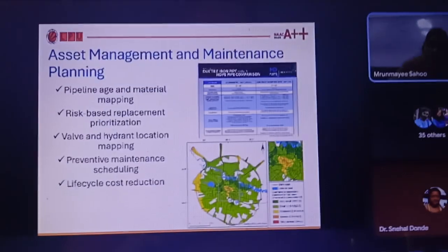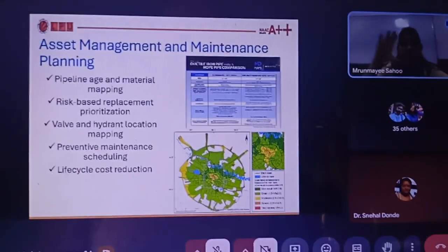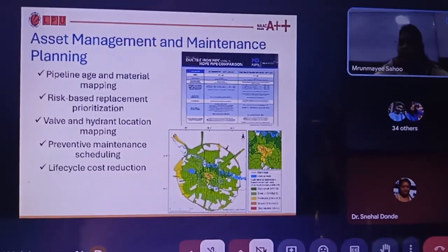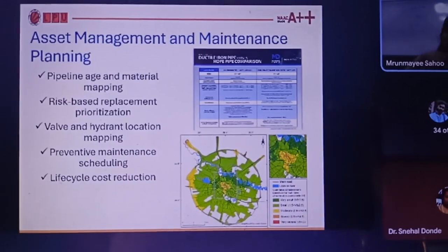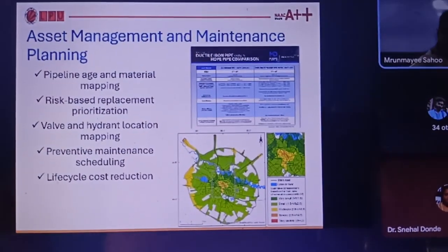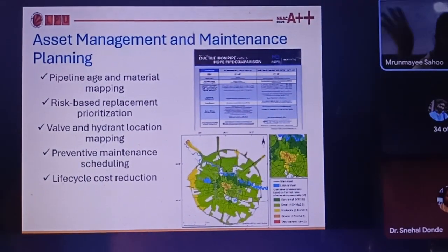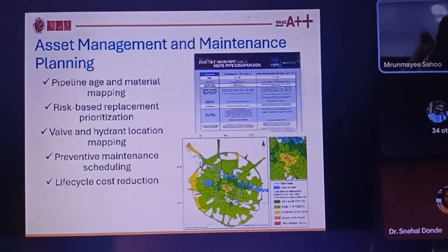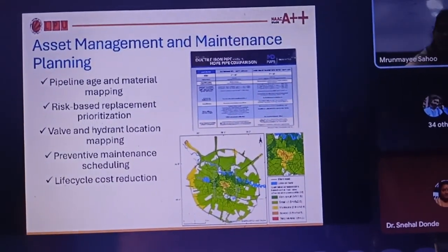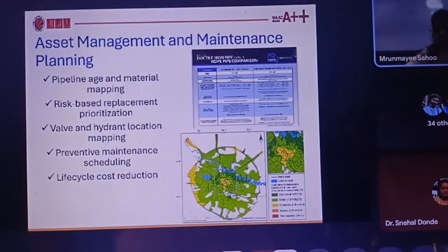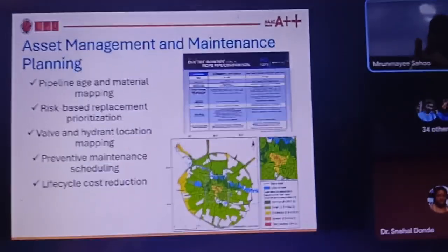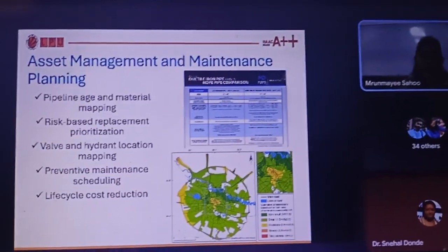So piezometers we use in the conventional way, and we measure the pressure head at each and every point of the pipelines before supplying it to you. So it's not an easy-peasy work, water distribution. It's literally water supply engineers who work on pressures to make your pressure perfect. Those kinds of things we can also do through pressure sensors nowadays, and those sensors will again be integrated with ML and integrated with GIS, so you will see in real time how the pressure is fluctuating.